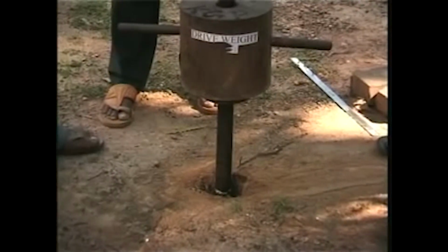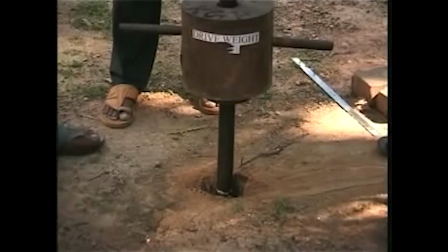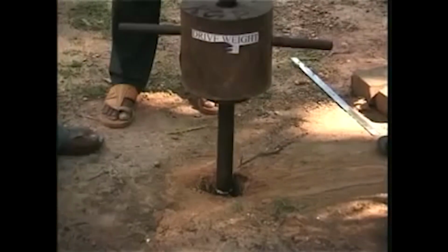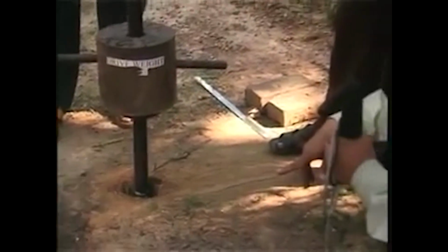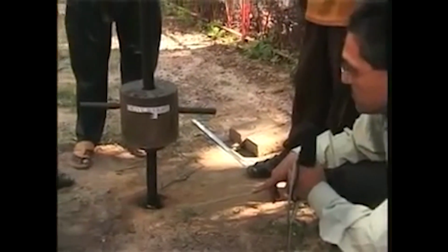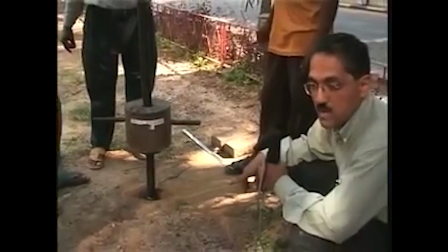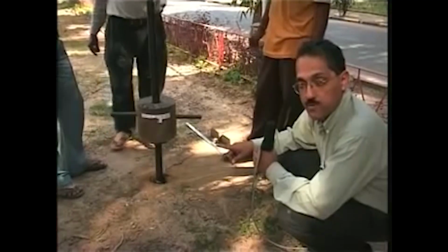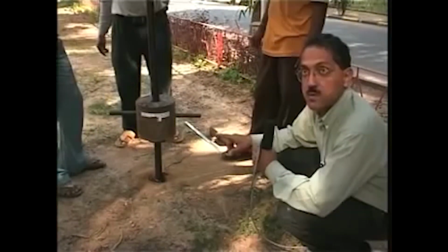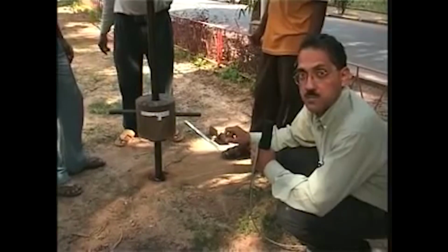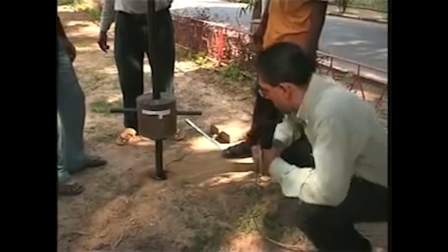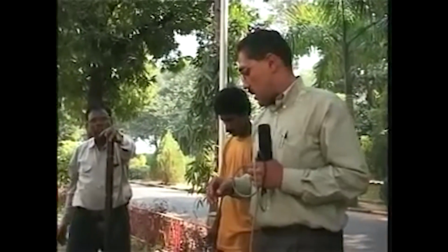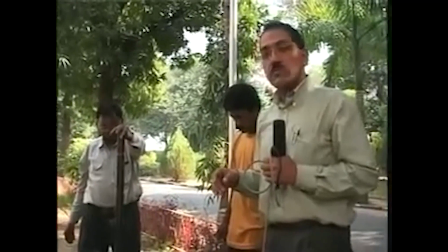So in this particular case, the raw SPT blow count is going to be recorded as the total number of blows required for the penetration of the second and the third 150 millimeter, which is 3. So in this particular case, the uncorrected SPT blow count is 3. Okay, so that's the demonstration of the standard penetration testing, and we are going to move on to the next demonstration now.